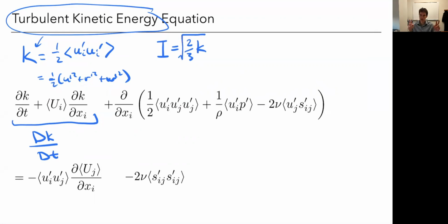So it's a root mean square, right? You could think of it as like an average, a root mean square, an average sort of velocity fluctuation. And then to normalize, since these are velocity squared, and then I square root it, so the units are velocity, I need to normalize by some velocity, and so we would normalize by the mean velocity, the average mean velocity. So this is the same concept, right? They're just scaled by some numbers, but same quantity, they're proportional, or at least with the square root proportionality. They're directly related.